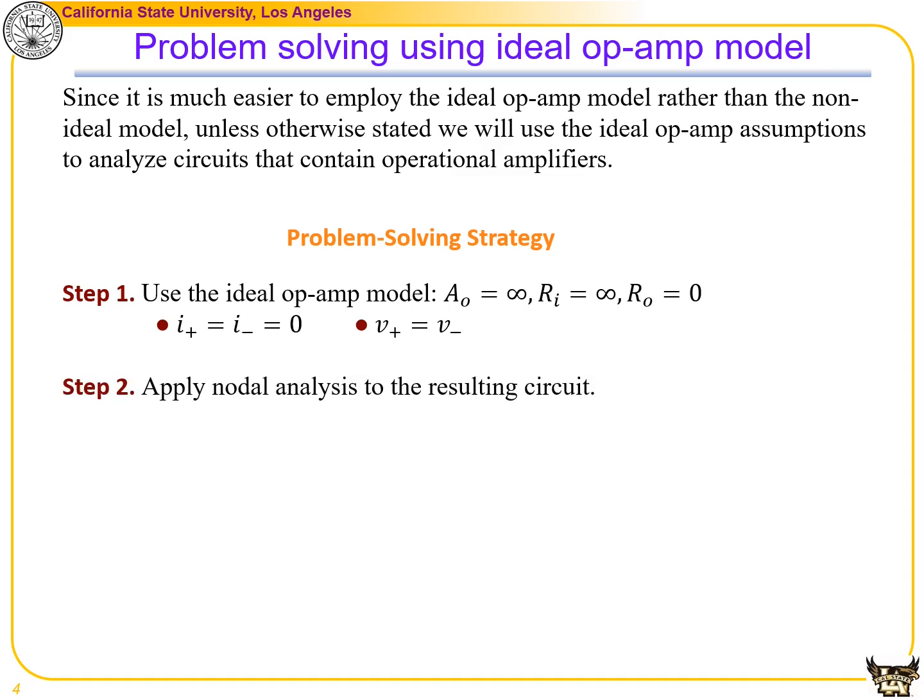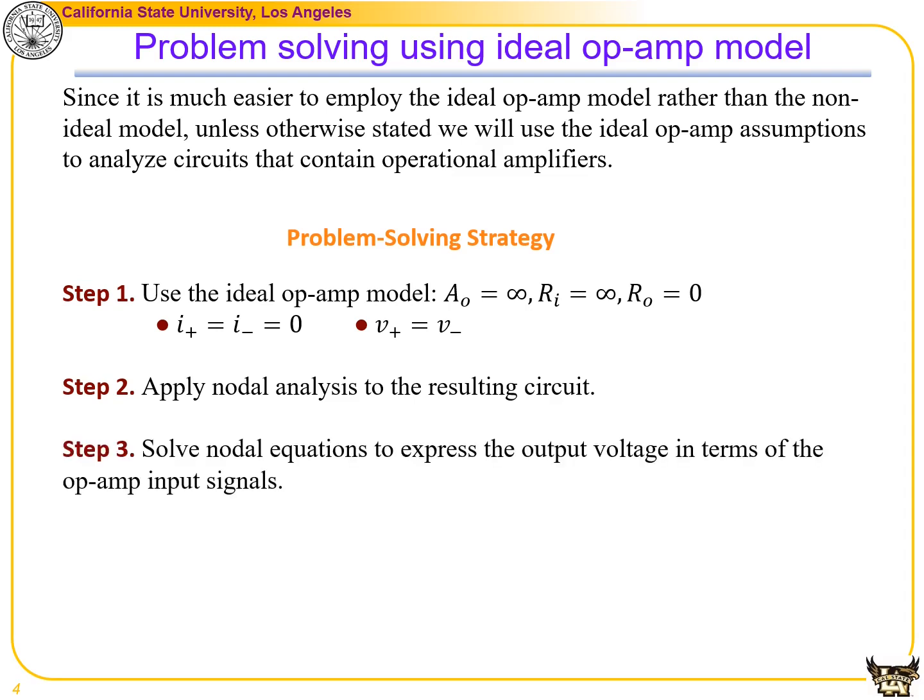The second step is to apply nodal analysis to the resulting circuit, or you can write KCL equations at different nodes. Step 3 is to solve the nodal equations to find the relationship between the output and input signals. And step 4 is to draw a conclusion.